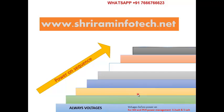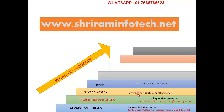Then the next signal is called the clock. The clock signal generates a clock frequency. Each chip requires a different frequency, which is generated by the clock. The CPU requires a different frequency, like 100, 200 megahertz. The PCH requires 48 megahertz, 66 megahertz, 90 megahertz. The SIO requires 32.7 kilohertz, 33 megahertz. So that frequency is provided by clock chips.